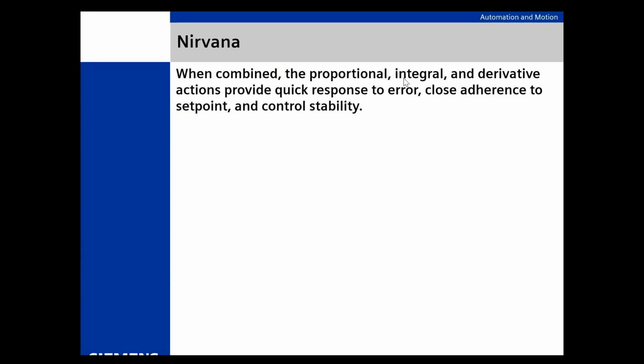The other thing about this is, let's say you've got a loop and it's wonderful. You go into a shutdown or some major maintenance going on. You bring everything back up and now your control ain't there. Before you mess with that controller, before you mess with that loop, find out what happened in the field.